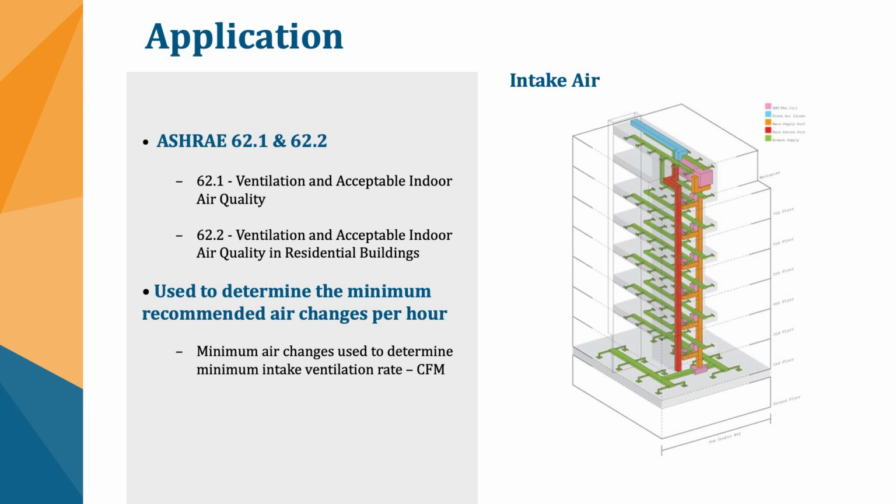Or you can do it a little more accurately by measuring the amount of intake air rather than just relying on the standards. You could do your airflow measurements just with the area of your ductwork and the set point for your fan, and just go off of that.